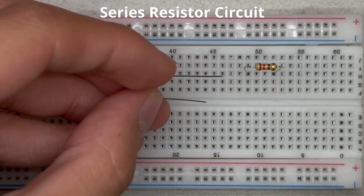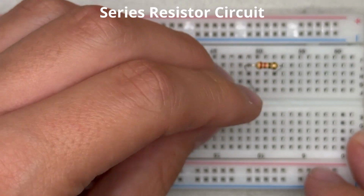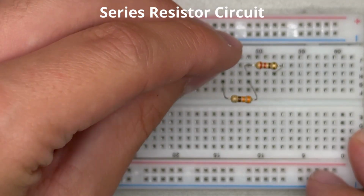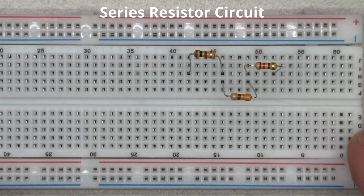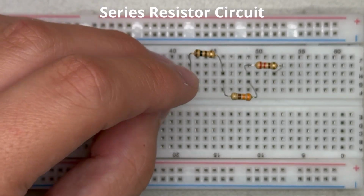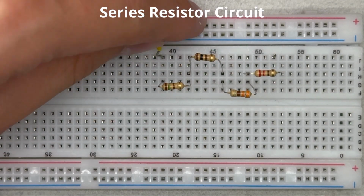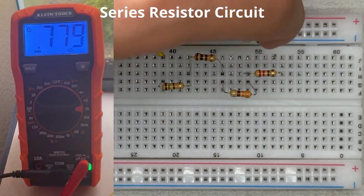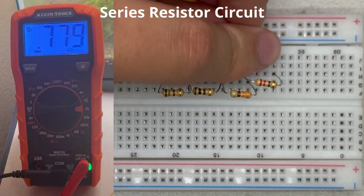What this looks like is basically just a line of resistors. As the electrons pass through these, each of them has to pass these rough bumps, and so the resistances of a series circuit just add up. The main concept you need to understand is that the current, which is the coulombs per second of electrons, is about constant among these, but there's a voltage drop you will experience from each resistor to the other until you reach zero on the other end. And here's the resistance we measured from a multimeter.